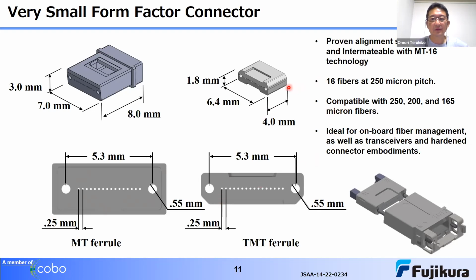And TMT ferrule also utilizes the proven alignment structure of MT16 and intermatability with MT16 technology. And standard fiber count and pitch is 16 and with 250 micron pitch.